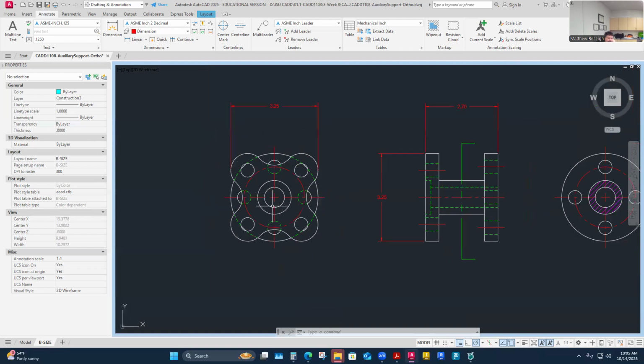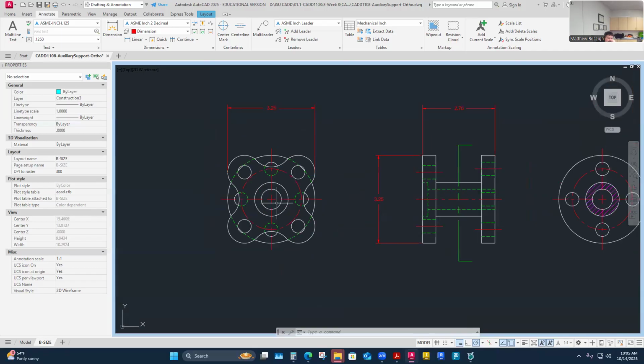What I like about this part is that it shows that when you have something like this, and let's say this was ten inches long, or a foot long, with a through bore going through it, dimensioning alone on some features is not enough. I'm going to dimension this and say what the diameters are, maybe what this hole diameter is, and that's all great and dandy. I'm going to base it off a control, like a center mark or a center line. But something like this really illustrates that there might be a necessary form control over it in order to keep this thing totally straight down through the bore that maybe has some substantial depth to it.